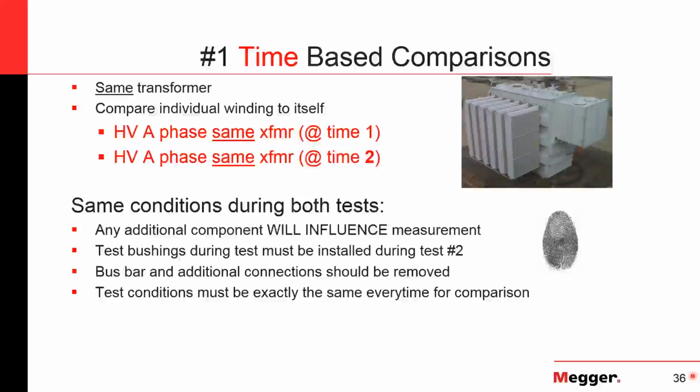And as I said before, it's an offline test. You want this thing de-energized. You want all the bus connections taken off because those can influence the test as well. So really for a time-based test, you want everything the same.